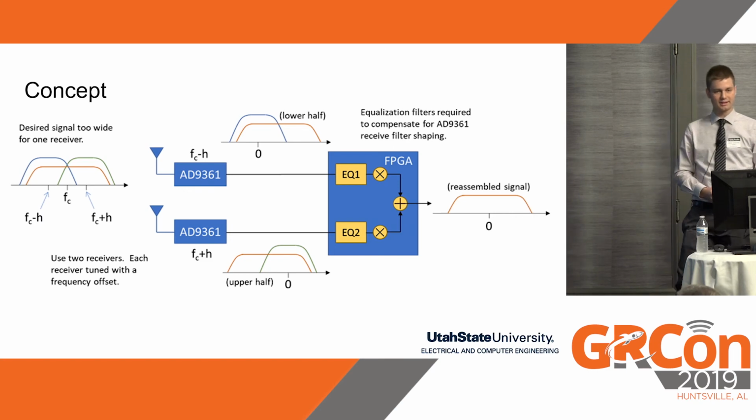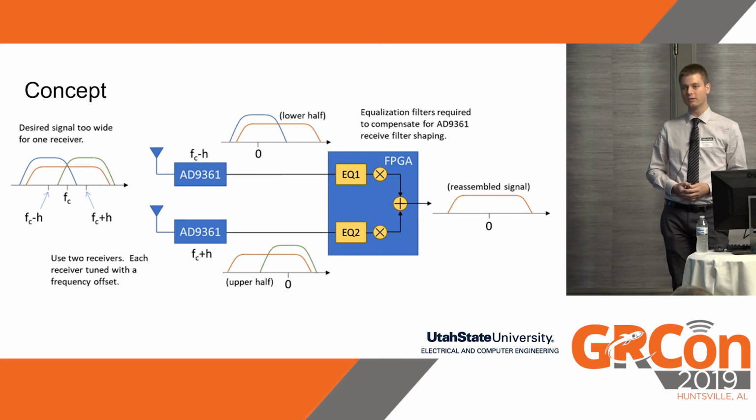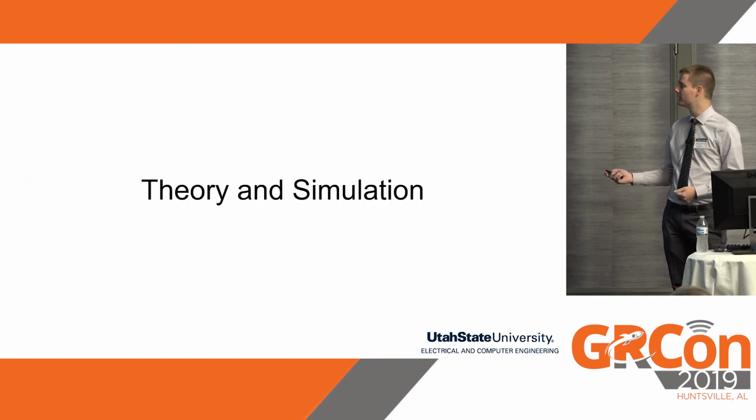And again, this is because if you look out on the market at what kind of commercial off-the-shelf software-defined radios there are right now, it's hard to find anything past 100 megahertz bandwidth or 100 megahertz sample rate. You're going to really start paying for it if you want to push past those data rates. And most of them are around 60 even.